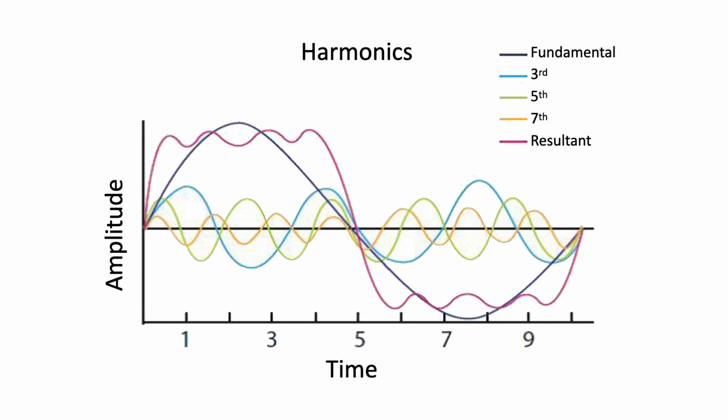Harmonic voltages and currents in an electrical power system are the result of non-linear electric loads. Harmonic frequencies in the power grid are a frequent cause of power quality problems. These in turn could result in an increased heating of the equipment and conductors, or the misfiring in variable speed drives and torque pulsation motors.